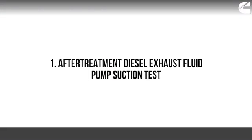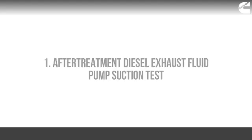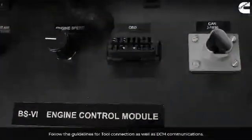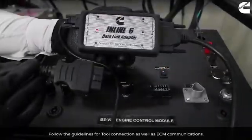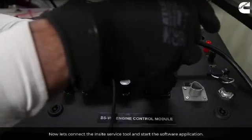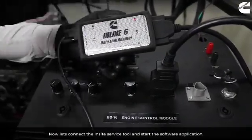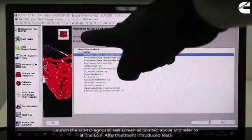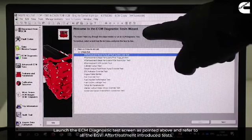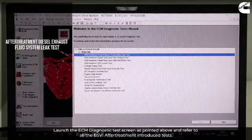After-treatment diesel exhaust fluid pump suction test. Follow the guidelines for tool connection, as well as ECM communications. Now, let's connect the INSITE service tool and start the software application. Launch the ECM diagnostic test screen, as pointed above, and refer to all the BS6 after-treatment introduced tests.